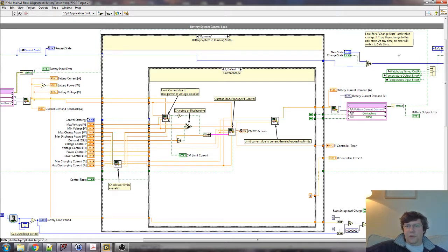A lot of the time when we're doing this sort of lifetime testing, you're just charging and discharging over and over and over and running cycles. If you have anything to do with batteries, or cars in general, automotive type stuff, you'll know about the NEDC and so forth. The NEDC is actually not great for batteries or hybrid vehicles because it doesn't really give the battery much chance to regen, or the car much chance to regen into the battery. But that's by the by.